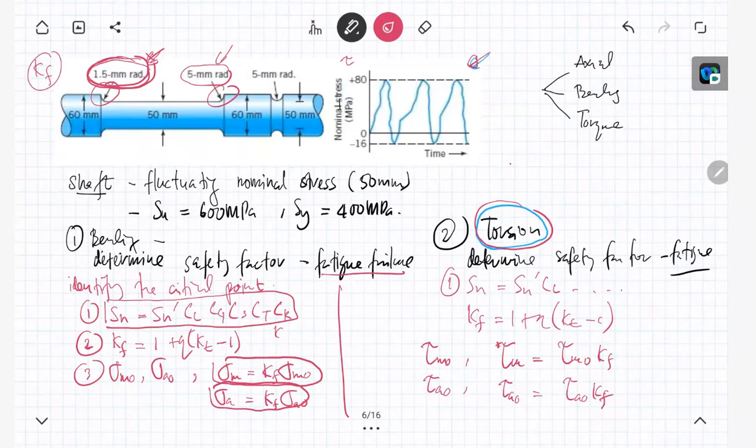So the same value that you get, the same procedure, same method that you have been using for torsion and bending. Because they just focus on torsion. If it has torsion, shear stress, and bending stress, if you have this one and this one, okay, so you have to calculate using equivalent. If there is just one, just focus on one. There's no need to use the equivalent.